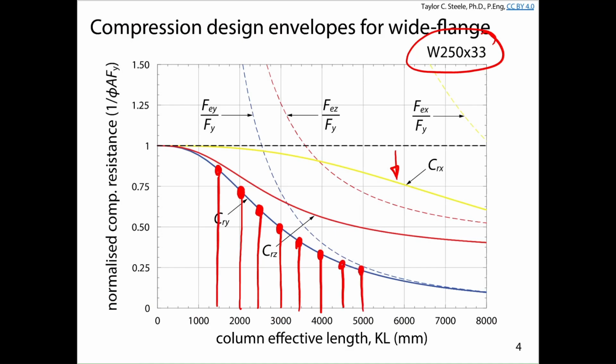For our effective length, we could look up the answer for compressive resistance for this particular section and see if we have enough strength. And what we're going to see is that in the handbook, there are some tables that are watermarked green on the edges. If you have your handbook, you can see that.